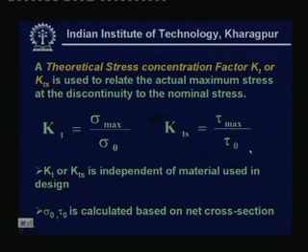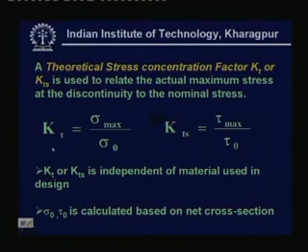Now, one thing is interesting: these stress concentration factors can be determined by just considering the geometrical aspects of the specimen, and thereby, as the word theoretical stress concentration factor indicates, it has no link with the material property. That means it is independent of the material used in the design.